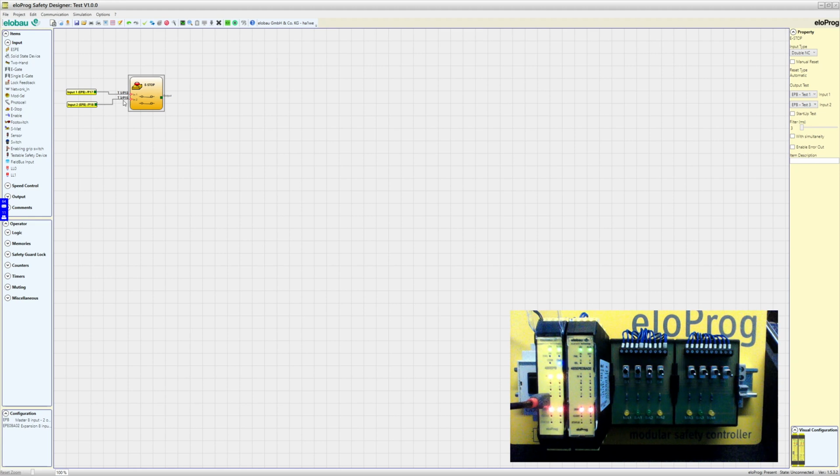They are time shifted, and they are testing if the test pulse which is applied here at pin 13 returns at pin 17. So you pick up your test pulse, that's the voltage supply for this contact at pin 13, the supply voltage in combination with the test pulse. You pick it up here at pin 13 and route it over the first contact and bring it back here on pin 17.